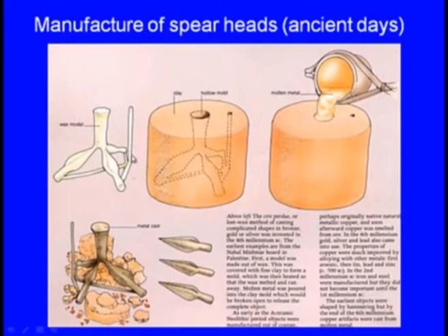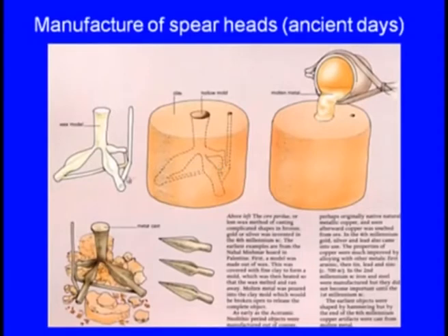After compacting the sand, they heated this system. Before that, they made a hole at the bottom. After heating the system, the whole wax melts and drains outside, and around that there is the compacted sand, which is mixed with clay, which has some binding action.